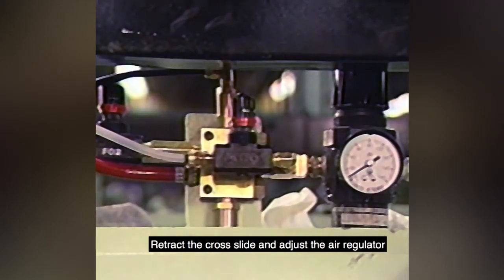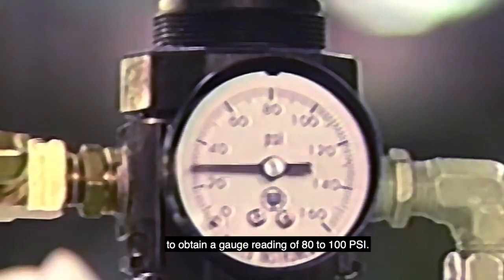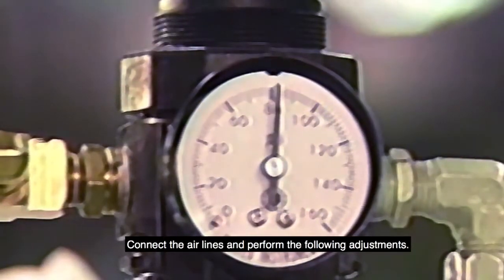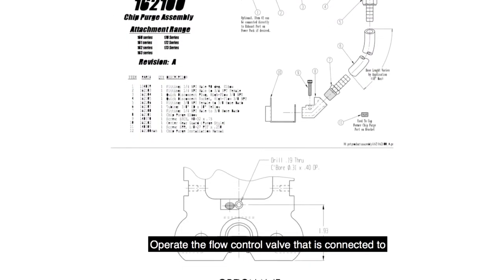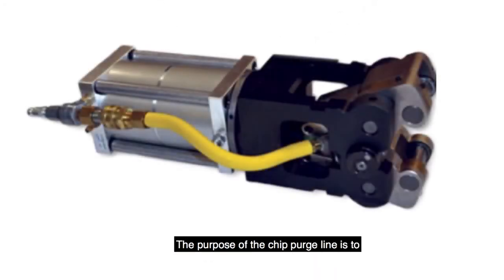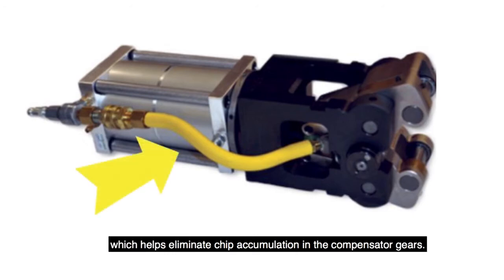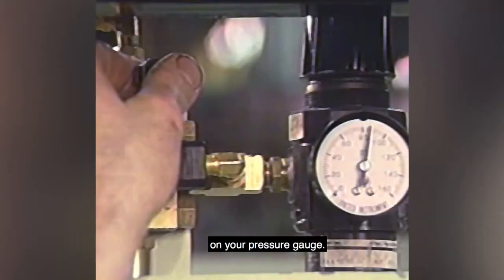Retract the cross-slide and adjust the air regulator to obtain a gauge reading of 80 to 100 psi. Connect the air lines and perform the following adjustments. Operate the flow control valve that is connected to the chip purge line. The purpose of the chip purge line is to pressurize the compensator mechanism area, which helps eliminate chip accumulation in the compensator gears. Open the valve until you notice a 2 to 3 pound drop on your pressure gauge.